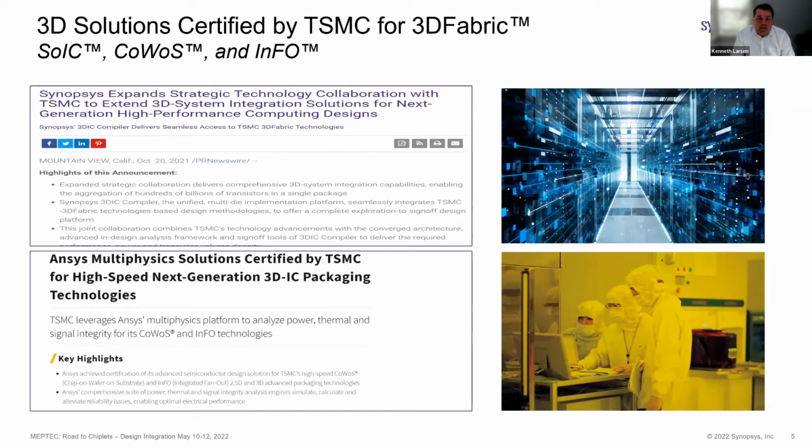So it's a new platform. We launched 3D-IC Compiler a few years ago. We are qualified and certified with the main foundries. Here are some updates on that. So it's not only SoICs, but we are talking about stacking 3D chips on top of each other using direct bonding or hybrid bonding, but it's including also the entire stack for CoWoS and InFO as an example.